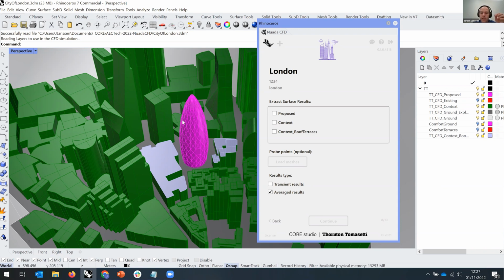Because if I get pressures on the facade, SimScale on their platform side does another meshing based on the mesh resolution of the CFD simulation. And for a building like this, depending on your resolution, you could easily get a mesh of 100, 200, 300,000 faces back. Very fine. You probably just want points every half a meter or so, or every 30 centimeters, which you can then also compare with, if you do a full thermal analysis, your UTCI comfort values, right? You have points you want to compute it with. So that's where my thinking came in from here.